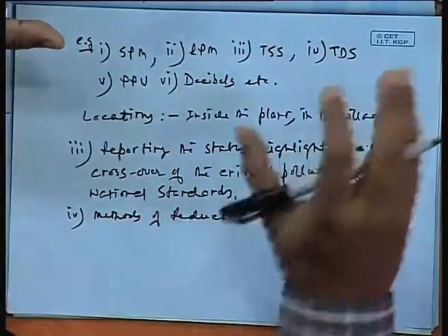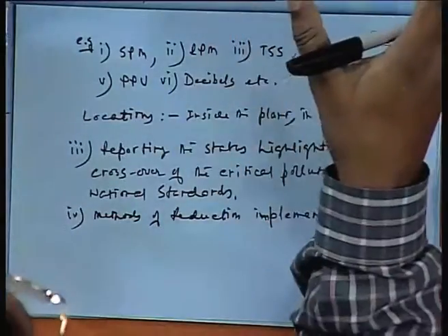When this EMP is generally given to the government, the company says how it is going to do the EMP. For example, how I am going to measure the peak particle velocity, whether per blast or for every 2 blasts. It would mention that I am going to follow a certain standard and stick to this rule. These are very, very important things.